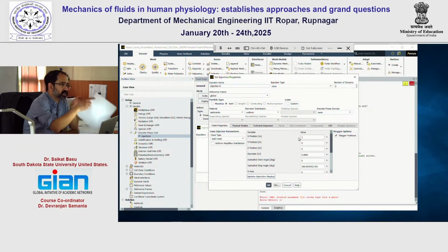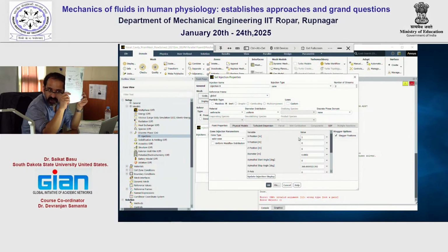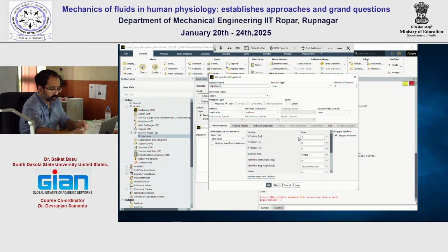So these coordinates that you see are from the ICEM world. Remember? That was in mm, while in Fluent we reside in the meter world, and we did that rescaling when we brought the machine. So we have to do this rescaling for these coordinates as well. So this would be 0.0, correct me if I'm wrong, 0.015,